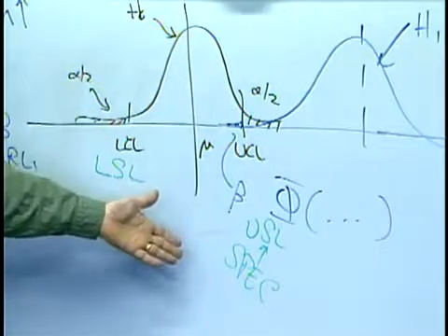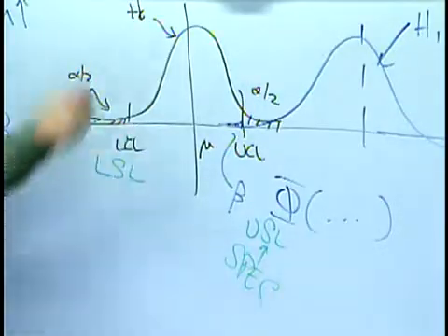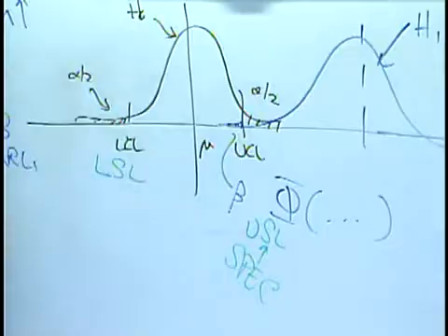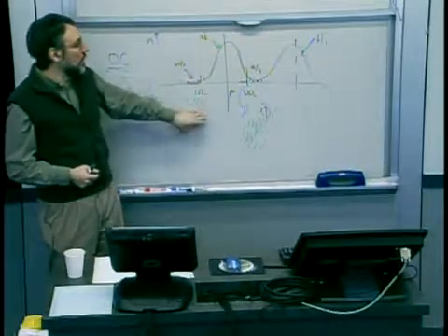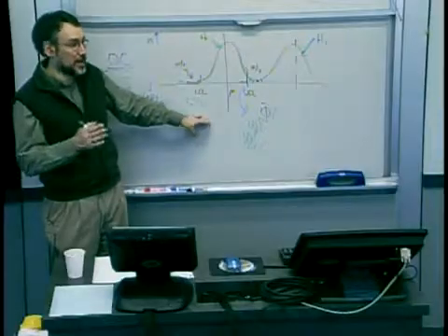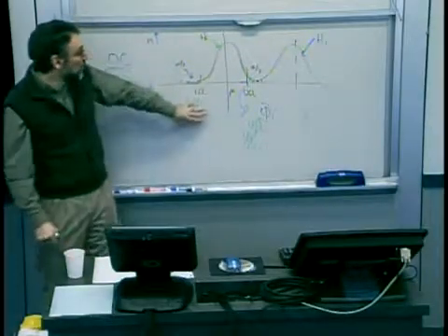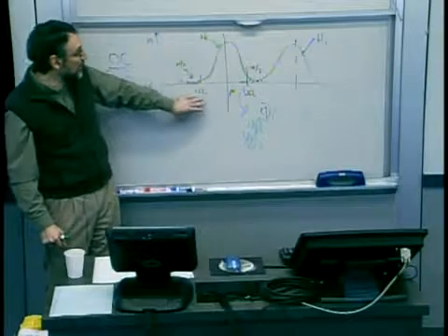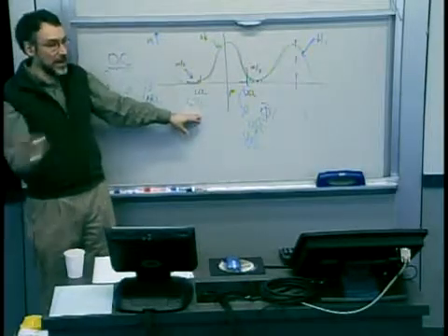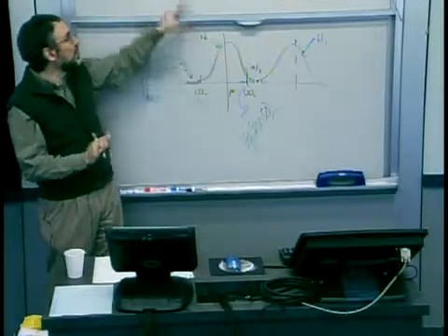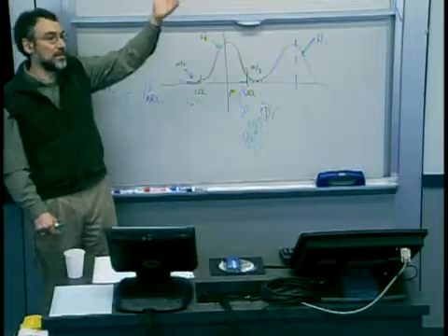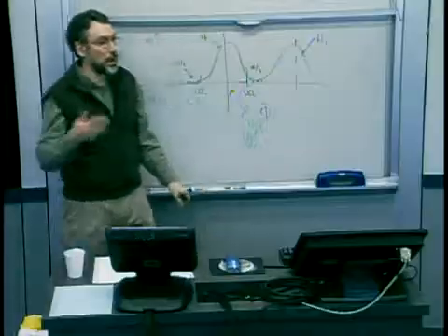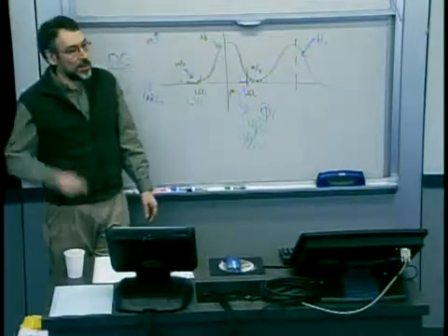And so nominally, your spec limits wouldn't actually change if you're changing sample size, right? The part still needs to function correctly within a certain band. So in that case, you change sample size, your spec limits would not, but what people often do is erroneously set the control limits to equal the spec limits. And that's wrong. What you want to do is set the control limits based purely on the statistics, based on your false alarm rate: the chance of observing, by chance or by random probability, an unusual event.